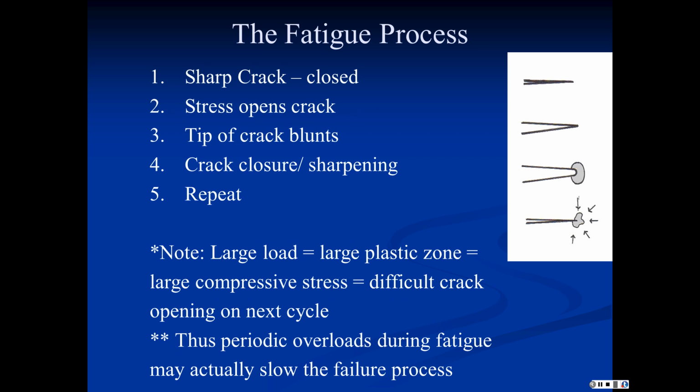Now, an interesting little tidbit. If you have a really large load that's applied, you're going to get a really big plastic zone. Remember, the equation from fracture was the plastic zone size is proportional to the square of the stress intensity divided by the yield strength.